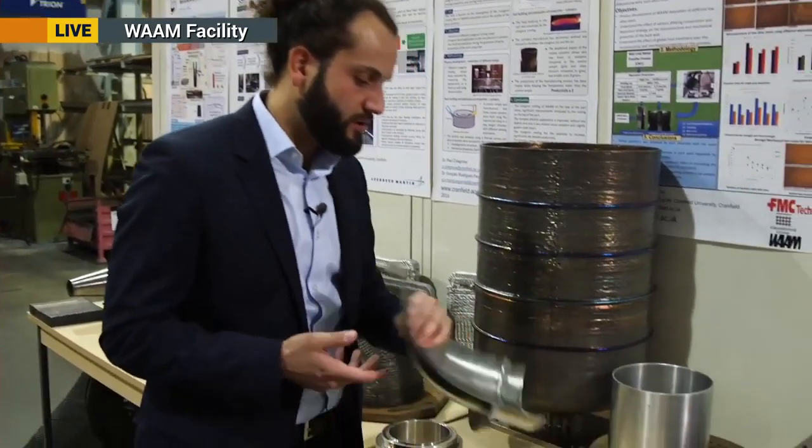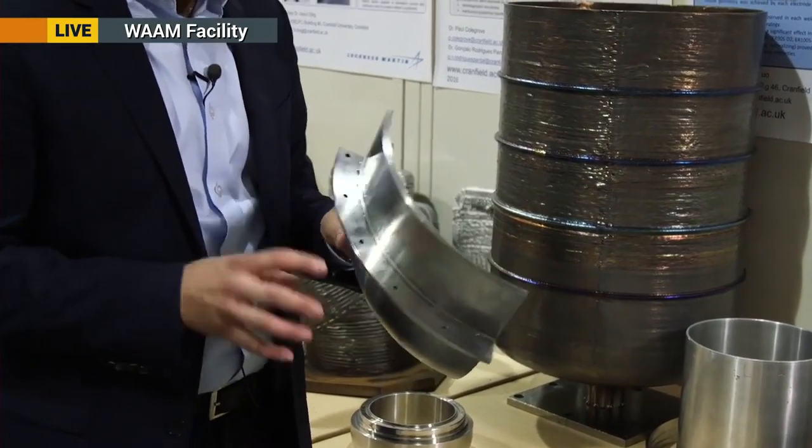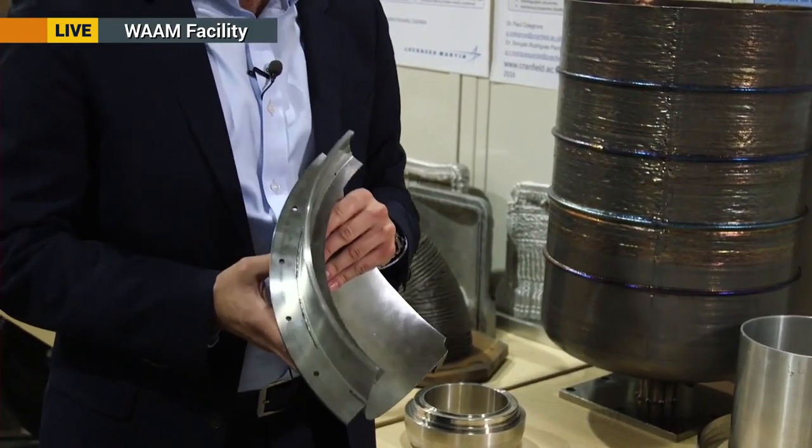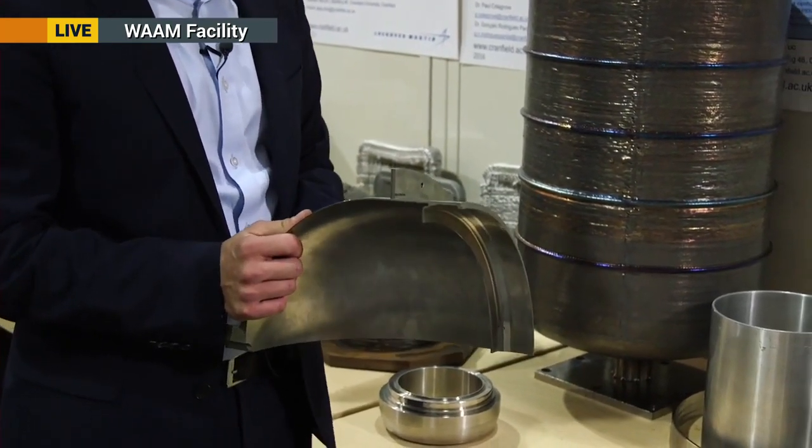And just for your information, that's how the tank will look like after it's been finished machined. In particular, this actually is a fuel tank for a satellite. Another attractive point for this component was that because you are no longer constrained by the set of forging tooling that you need to have if you go down the traditional route, now you can change the shape and the size of your tank to match the requirements of the mission. So again, you can minimize the amount of fuel that you take to space. And again, each kilogram that flies to space is about 10,000 pounds. So if you can reduce some weight, you're also reducing your expenditure.